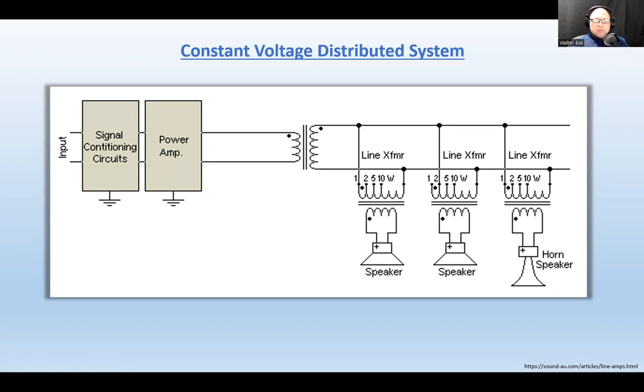But in order to be able to connect it in a way that makes sense, and what I mean by that is the ease of installation, or the simplicity, or the practicality of installation. Remember when we could do a bunch of speakers and you can connect them in series-parallel combination, and yes, you can accomplish the required impedance to be plugged into the output of the amplifier.